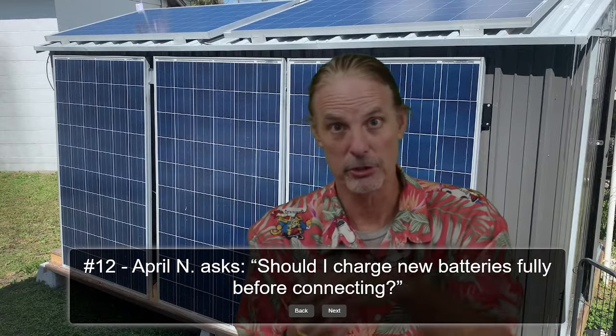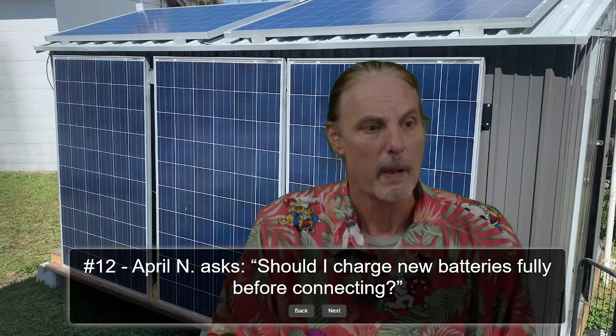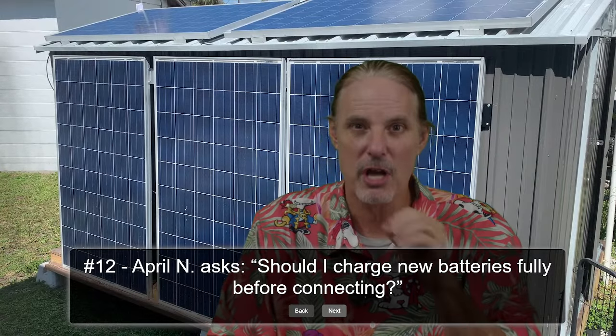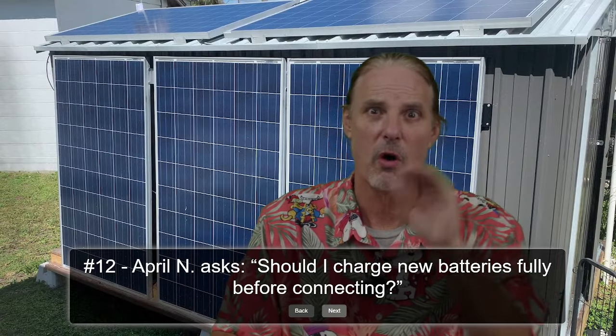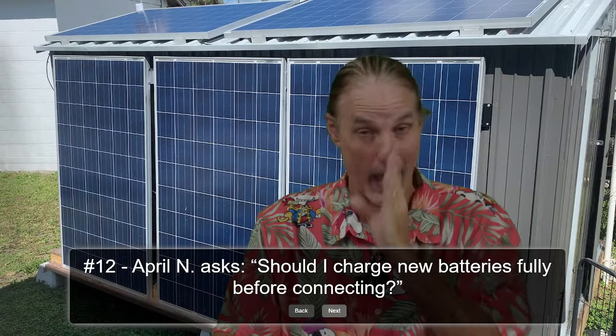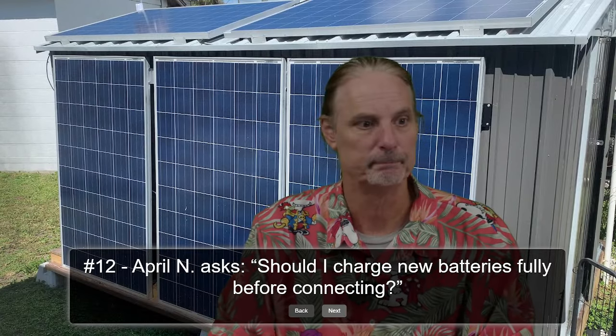You may pull too much energy from the little battery going into the big batteries. So that's something to consider. But the answer is yes, you should charge them all the way to full. If you're not sure if all the voltages are the same and if all the stated charges are the same, then absolutely you should just go ahead and charge them all up to full and then add it then.